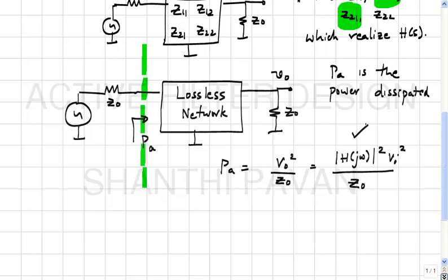Okay. This is now presumably a lot simpler problem to solve than trying to figure out 3 functions of S, Z11 of S, Z12 of S and Z22 of S, which is what you would have to do if you assumed the general 2-port and then tried to figure out the 2-port. We'd have to do something very complicated.